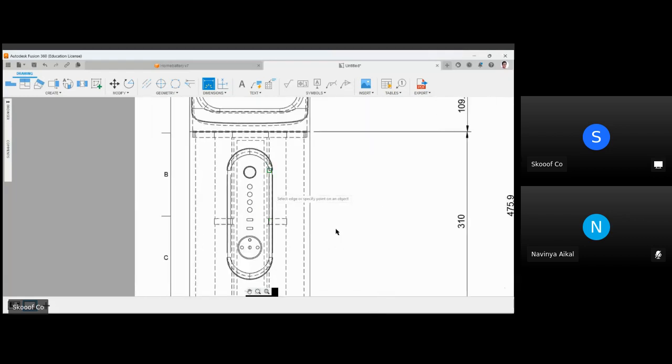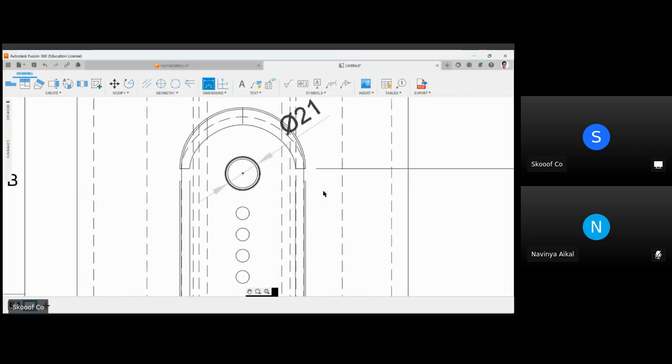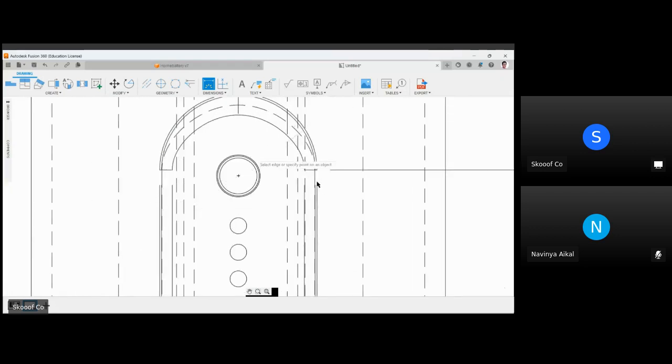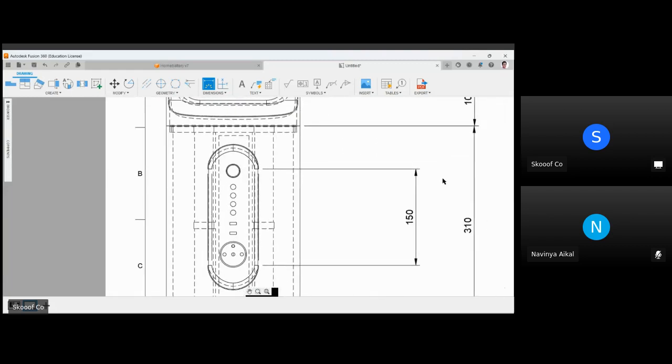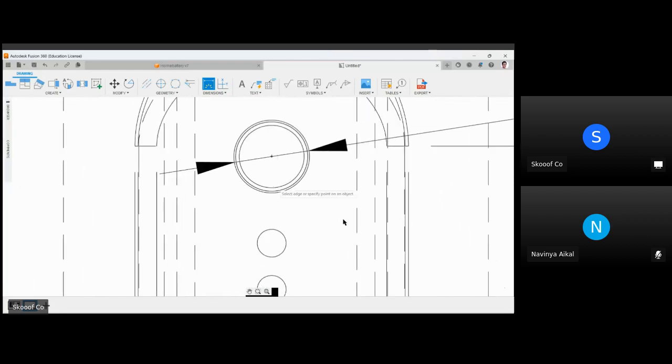So we have to do this part, right? Now again, these are squares and circles, right? So we have to give them a radius. Once you keep your mouse at the surface edges in the arc, you will see the diameter has been provided. Click on that, like this. Again, there are inner diameters as well. So we will do that as well.